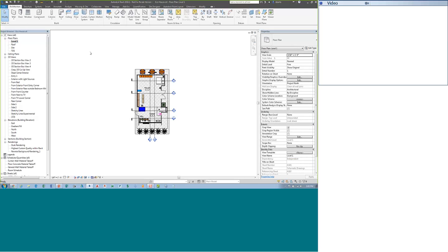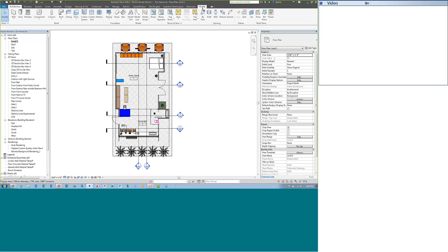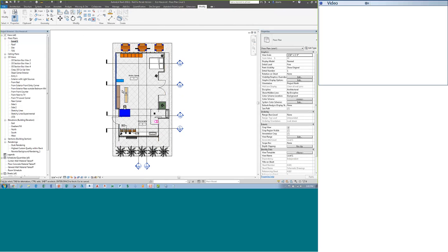So the first command that we talked about is the delete command. How do we delete content? Very easily, head over to the Modify tab, Modify panel, and hit this delete command. Start the command, pick an entity, hit Enter or spacebar, and the object is deleted.